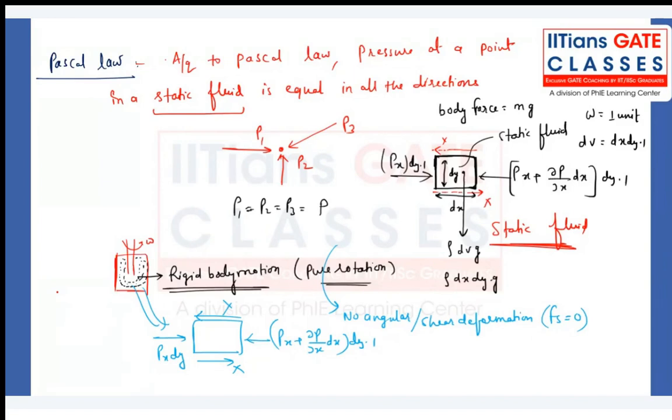That's why you have the Stokes hypothesis. Do you know it? Tell me, guys. Any one of you know about the Stokes hypothesis? Till now we have discussed only the first coefficient of viscosity, that is dynamic viscosity, right? We have not talked about the second coefficient of viscosity, that is lambda, which denotes the volumetric deformation of the fluid element. So this basic concept and understanding must be there when you are dealing with the derivation of the Navier-Stokes or any other equations.